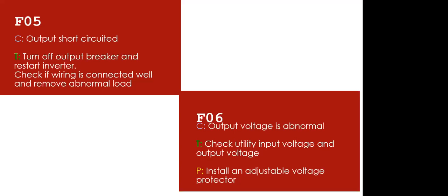So to troubleshoot it, you have the battery breaker, firstly the output breaker. That is why it is necessary for any installation to have breakers for easy troubleshooting. You turn off the output breaker, you turn off the input breaker, then on your inverter you turn off the battery.